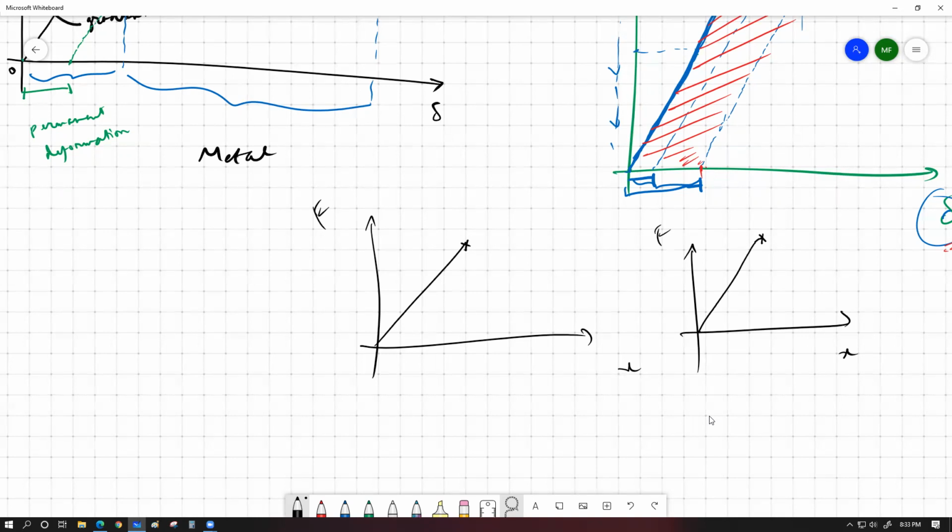Diamond is also a highly brittle substance. It's pretty strong, but it's highly brittle. You have to understand, kids, one thing that I really want to make sense with you. You need to be able not to confuse between strong materials and brittle materials and ductile materials. This is really important. Let me give you a simple example. Anything that can withstand a large amount of force before showing any type of deformation, or any object that takes a huge amount of force to deform even by a little bit, is generally called a strong object.